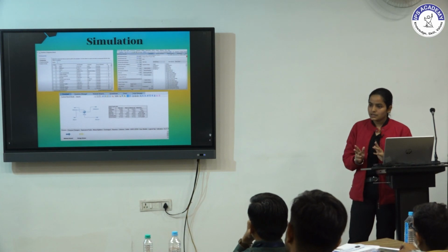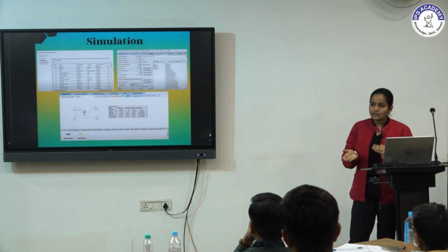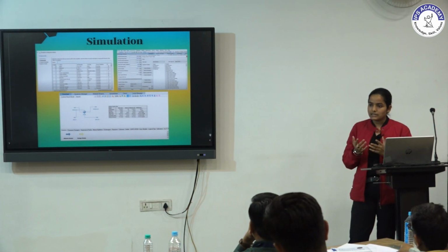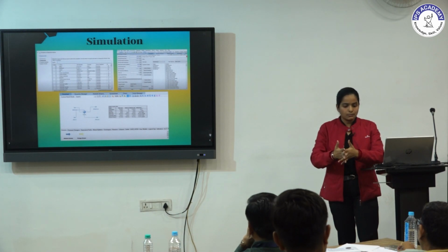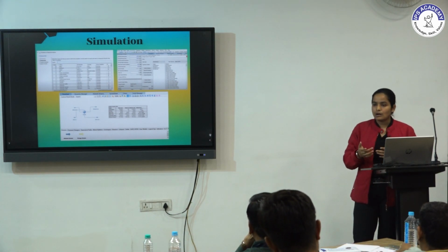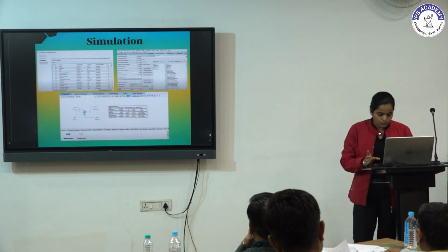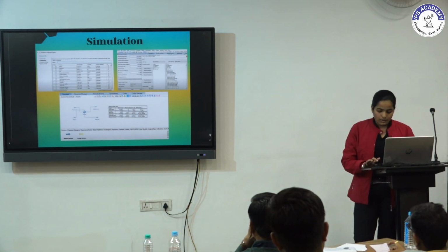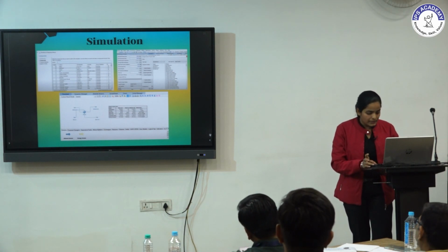Two more material streams should be introduced and further named as methanol out and water out, and all the 4 material streams should be connected with each other. And now we should move further. We have used Raoult's law as our property package, because a property package also has to be chosen in that. Similarly, all the desired data is mentioned at the places.